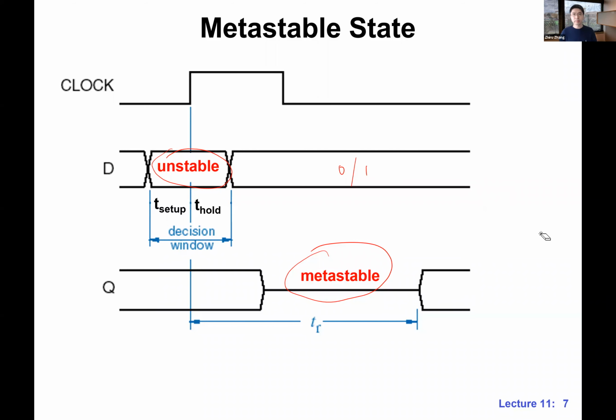Okay, but for some reason there's this glitch, this hazard, we call it a static hazard. F is making a dip temporarily, we call it a transient value, from 1 to 0 and then back to 1. Really the reason is, see here, you want to look at this part. This is where we are seeing the transient. For a certain period of time, both of these terms are 0. That's why we are seeing this dip, where F is going down to 0 for a moment.